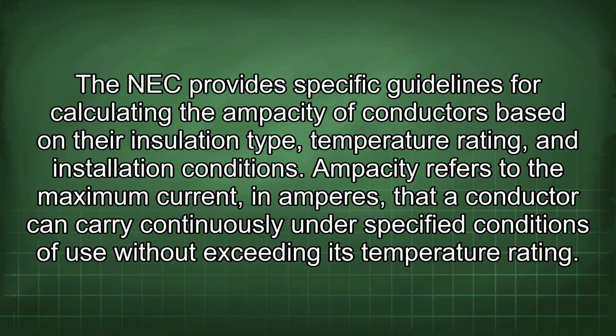The NEC provides specific guidelines for calculating the ampacity of conductors based on their insulation type, temperature rating, and installation conditions. Ampacity refers to the maximum current, in amperes, that a conductor can carry continuously under specified conditions of use without exceeding its temperature rating.